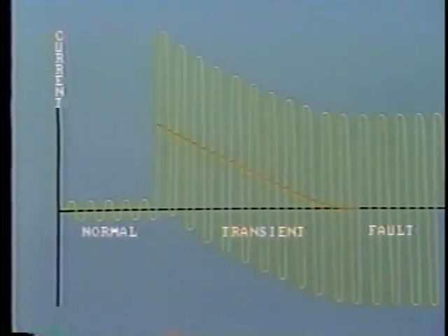For example, this small sine wave represents the value of current under normal conditions. And here we see the same sine wave, but with much greater amplitude due to the fault on the line. Indeed, this may be high enough to cause saturation of the CT's iron core. However, there is yet another factor to make matters worse. Between normal current flow and stable fault current flow, a transient is created like this for perhaps 15 to 20 cycles.